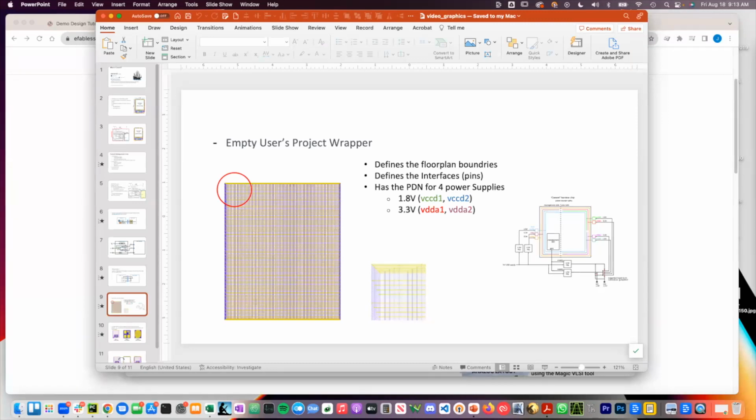How do we input 5 volt to the chip? SkyWater provides 5 volt devices as well as 3.3 support for 5 volt as well. So in the Caravel IO, not in the total library that exists in Sky 130, we have 3.3 volt IOs that are over voltage tolerant up to a certain level. So you can stress the IO up to a higher voltage. There's also a dedicated high voltage IO, a 5 volt compliant over voltage IO that's intended to be used for things like I2C, and that is not currently the IO that's on Caravel.